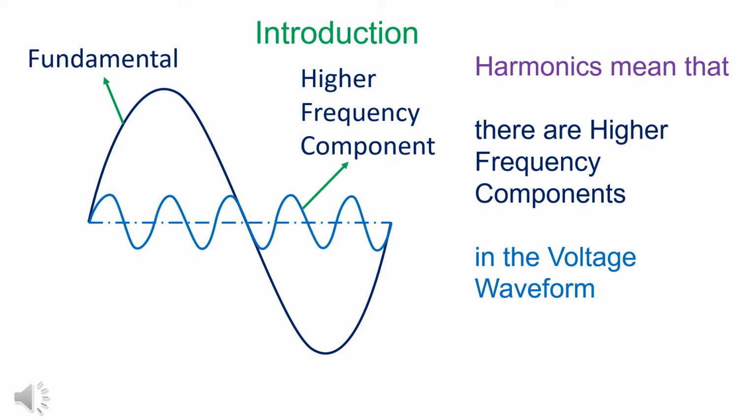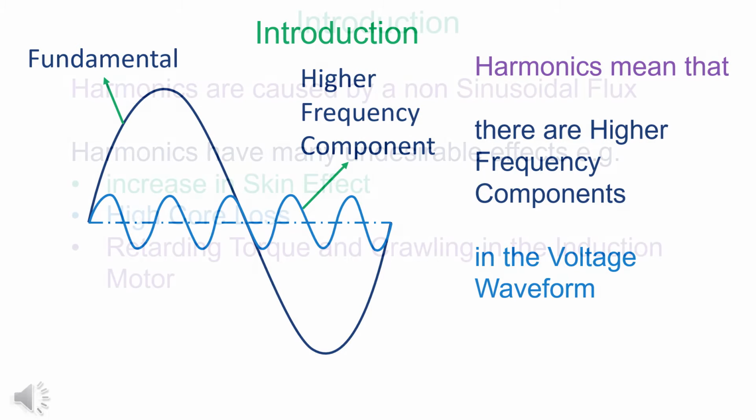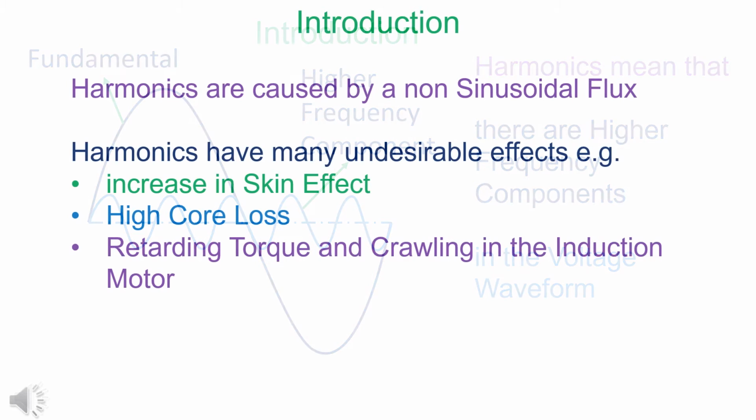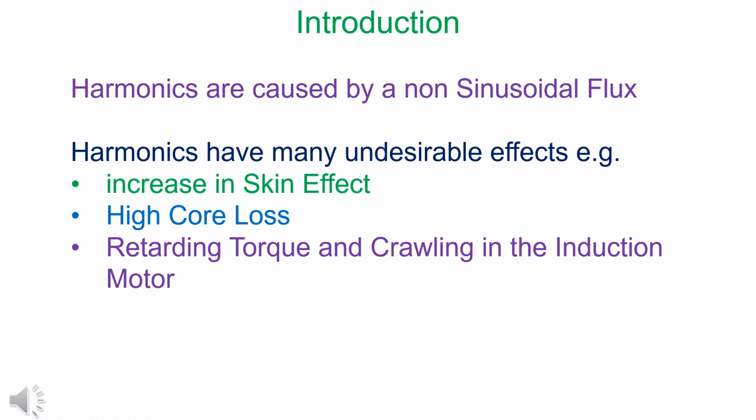Harmonics means that voltages of higher frequency are also present in addition to the voltage of the fundamental frequency. The harmonics are caused by a non-sinusoidal flux. Harmonics increase the skin effect, they increase the core loss, they produce retarding torque and cooling in the induction motor.